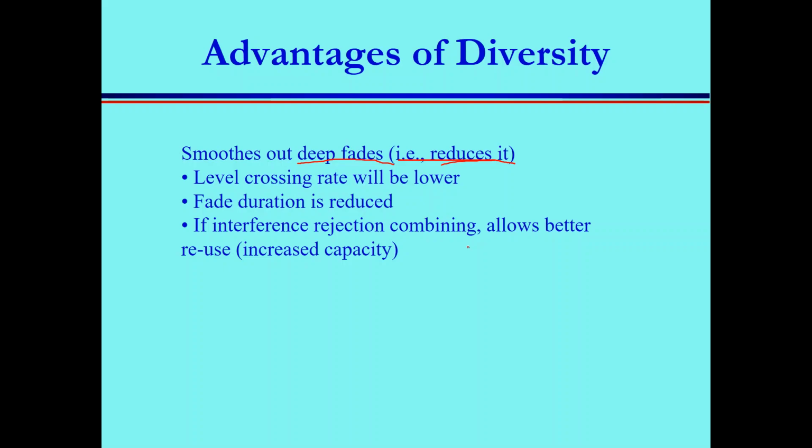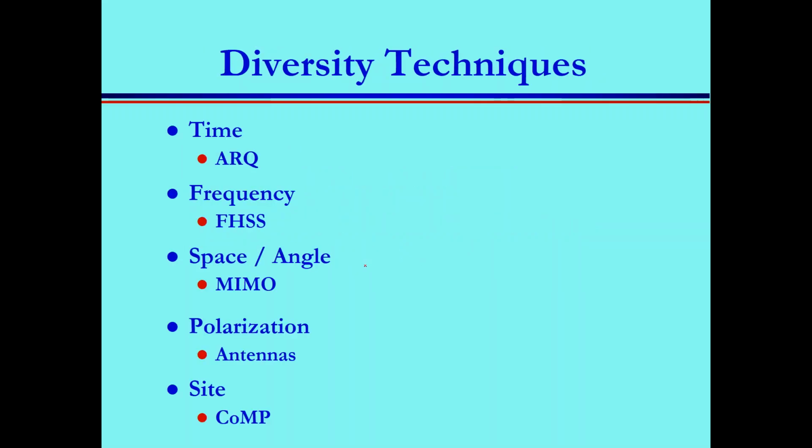Everybody also must know and remember why fading happens to be able to solve it. Since we have fading, we have two ways to solve it: either to adapt to it, cope up with this problem, or try to reduce it. This technique, diversity, reduces it. And it can really eliminate it if you use massive MIMO. Somehow, not perfectly, but to a huge degree, you can really reduce it significantly.